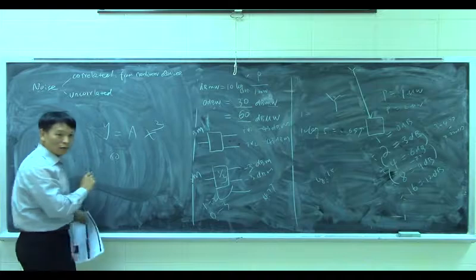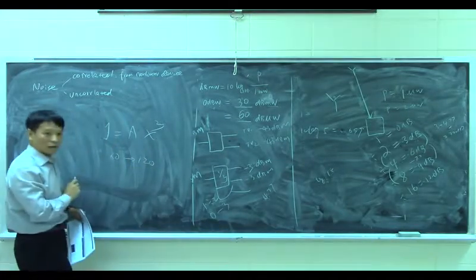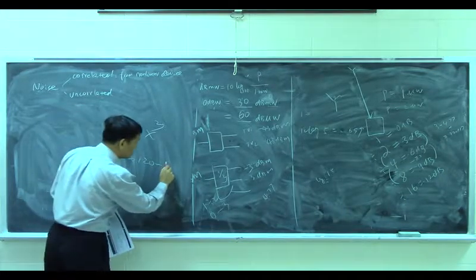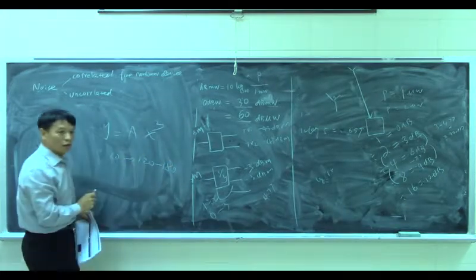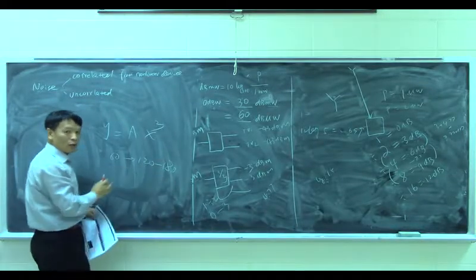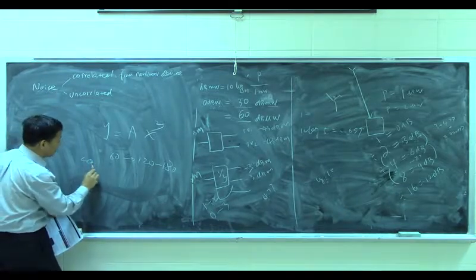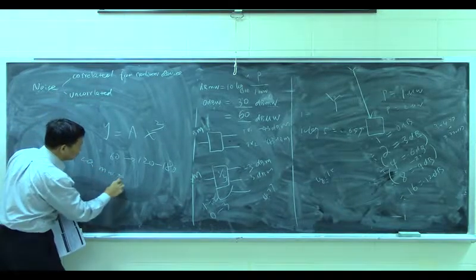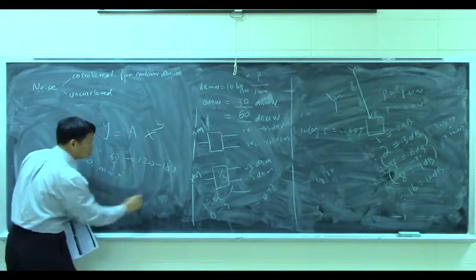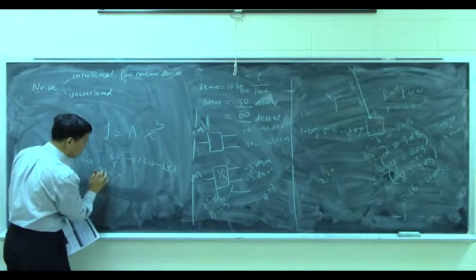So that's why, if your input signal is, for example, 60 hertz, then you are going to have another one, 120 hertz. That is called a second order harmonic. And possibly you have another 180. This is 3 times of this, so that's a third order harmonic. Like we said in the beginning, cosine m omega t, so omega equals 60, this m equals 1, this m equals 2, this m equals 3.